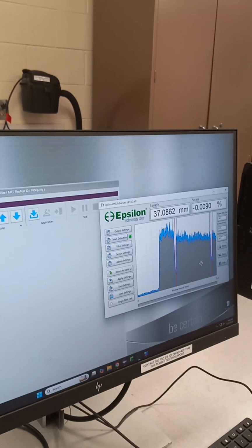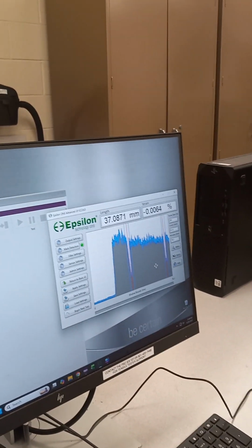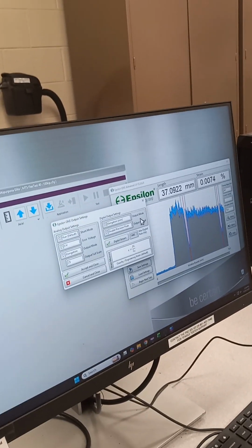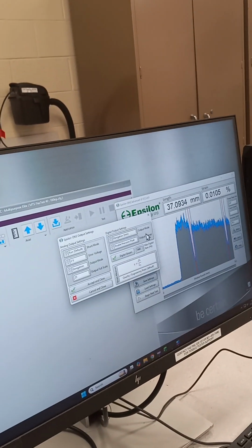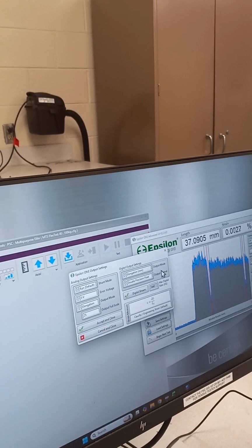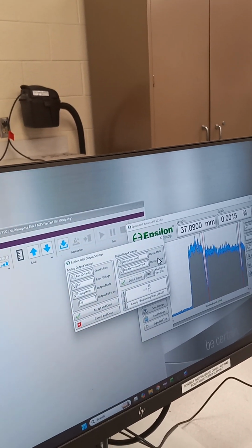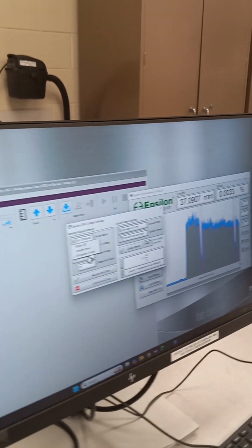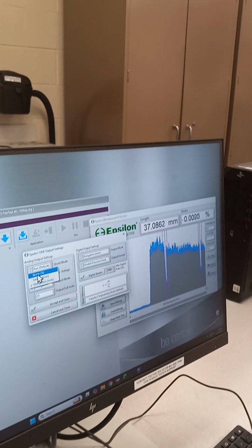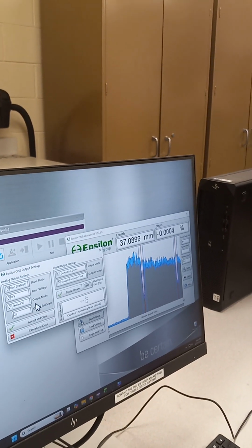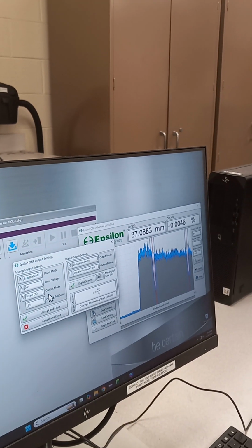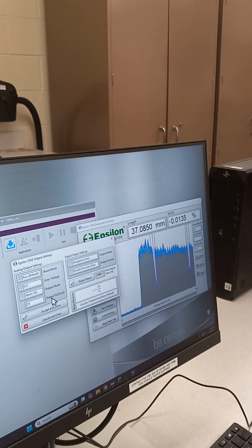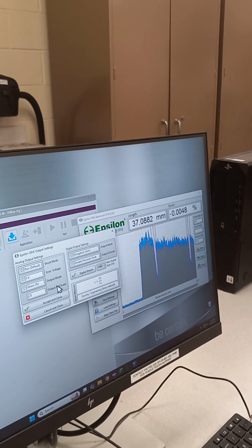Okay, so we've done mark detection, sensor settings, and the last one is output settings, at the very top. This one is to tell the DAC system what information we're sending from the camera. The first thing we need to choose is what we're sending out, and we're going to send out % strain. I guess we can send out whatever you want, but that's what most of the other materials people had us do in the past. And we're going to choose what the output full scale is.